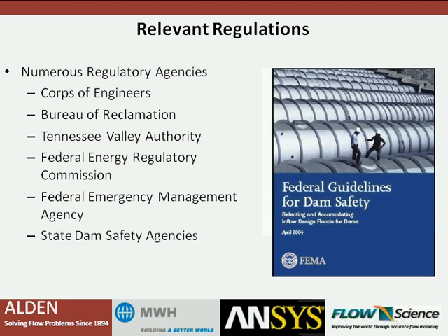So the next question we might ask is, what regulations might apply to our dams, either existing dams or new dams, when we're looking at designing spillways in particular? Well, that depends on a couple of things, and it's the type of ownership, whether it's a federal project or a non-federal project, and then the type of project itself, whether it's a power project or a non-power project.